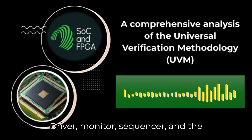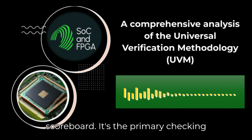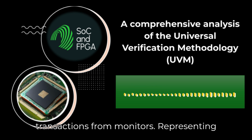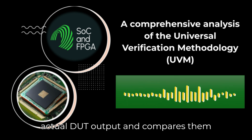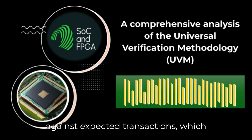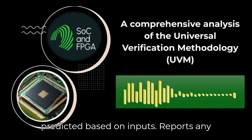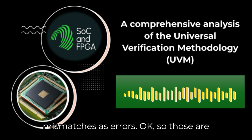Got it. Driver, monitor, sequencer, and the checker. That's typically the UVM scoreboard. It's the primary checking component. It usually receives transactions from monitors, representing actual DUT output, and compares them against expected transactions, which might come from a reference model or be predicted based on inputs. It reports any mismatches as errors.